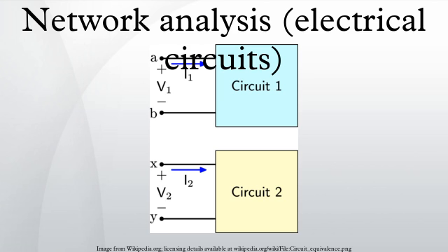Small signal equivalent circuit. This method can be used where the deviation of the input and output signals in a network stay within a substantially linear portion of the nonlinear device's transfer function, or else are so small that the curve of the transfer function can be considered linear. Under a set of these specific conditions, the nonlinear device can be represented by an equivalent linear network. It must be remembered that this equivalent circuit is entirely notional and only valid for the small signal deviations.